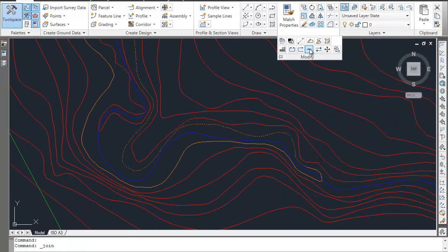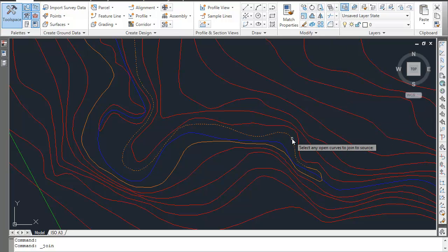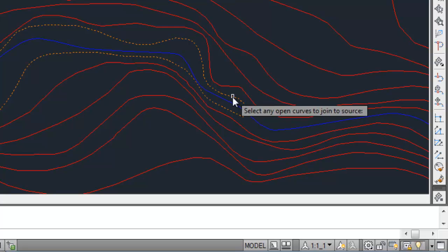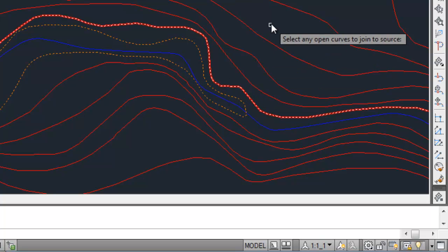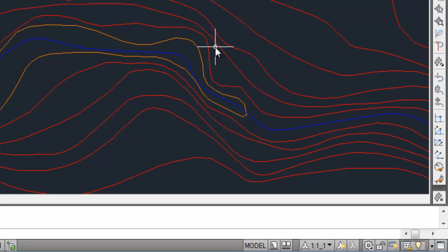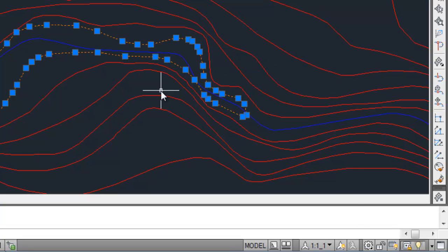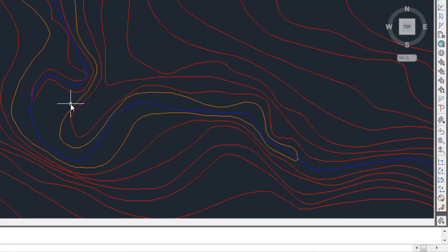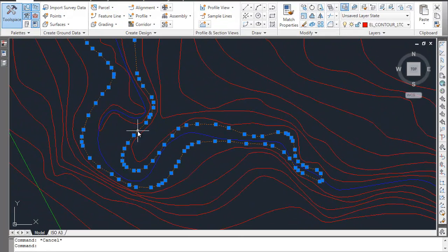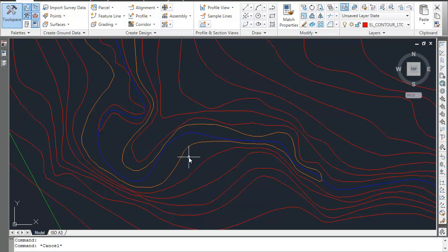When you select on that, it says any more to join together. You select the next one that you want to join and go through the whole thing. We're only going to select 2 at the moment, and press the return key, and it will actually disappear, but when you click on it again you'll notice that the whole thing is currently joined together now. That's good. So now we only need to select 1.